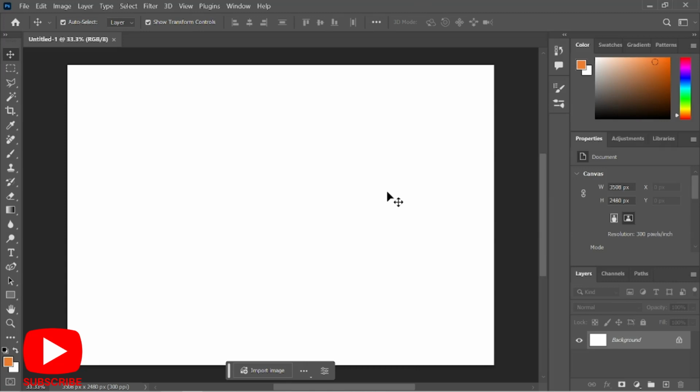Before you create the sheet, you have to set what we call guidelines. If you want grid lines, you can set your grid lines as well, because once you are creating a sheet, you have to leave some margin lines around it. You don't have to occupy the whole sheet; you have to leave some margins around your sheet. I prefer bringing in some guidelines, because that will make your work proportional and even.